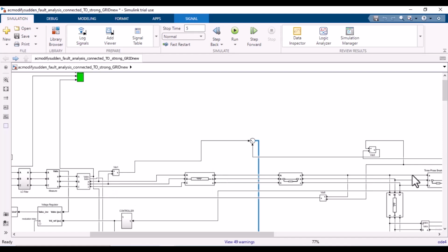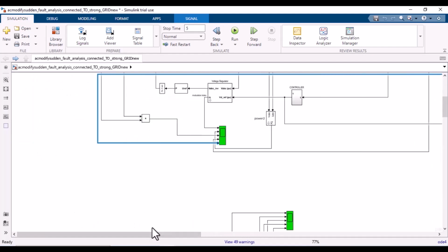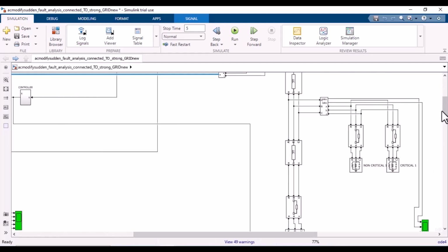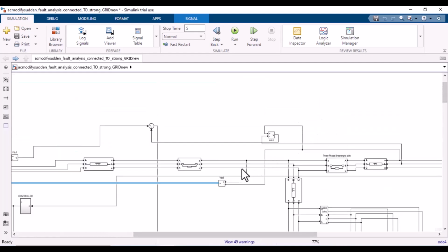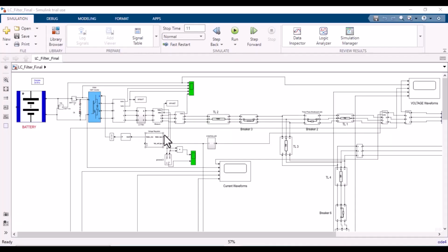Let's connect the first phase, phase A, before the transmission line and after the transmission line, connected to the main grid. So you can see here the comparison is reduced and almost becomes zero. These are the differences. The phase difference is improving and going to zero. We are using feedback pulses from the main grid, comparing the battery and the grid voltages, and we can find where the difference is. So in the starting, there is a difference.